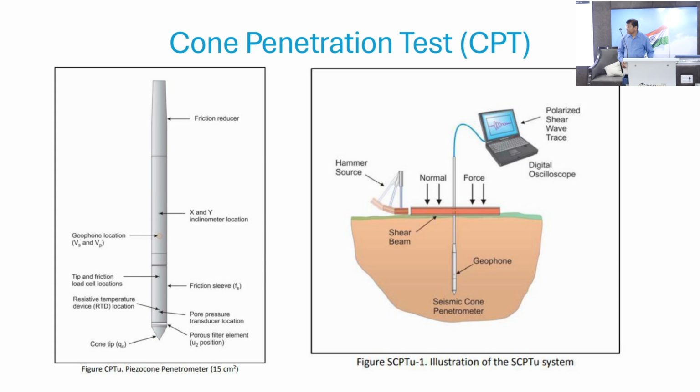And where we left yesterday, I want to touch a little bit on that. Yesterday we discussed a little bit about CPT. These are the two concepts we are saying: regular CPT or seismic CPT. In regular CPT we have only one cone, and once you do that, then go to the bottom, then we switch to the seismic CPT where we send a geo cone to the bottom and then scan it and collect, as I showed you yesterday, both the longitudinal and shear velocity.